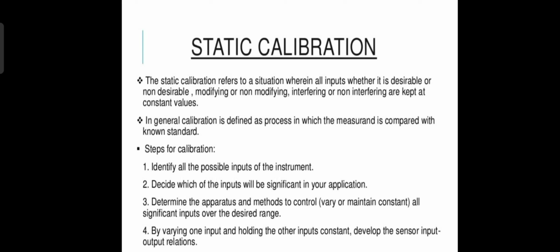The third type is physical end-to-end calibration. Physical end-to-end calibration is the best method of ensuring collection of valid data. Engineers generally perform this calibration after installing the transducer in the actual instrument where it is to be used. It mainly checks the measurement system installed on the test article so that the engineer can identify and correct many potential problems at an earlier stage.